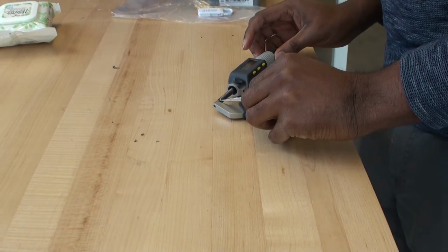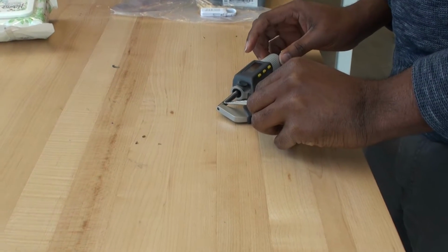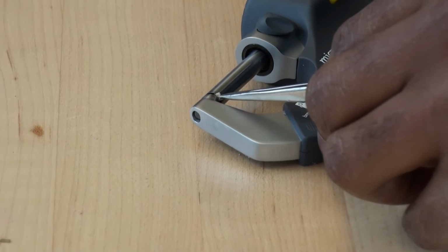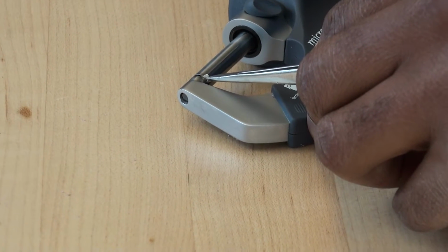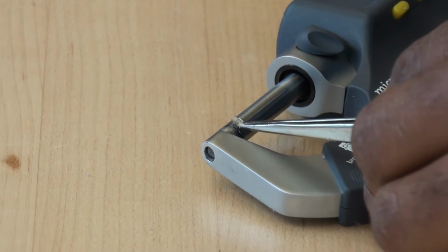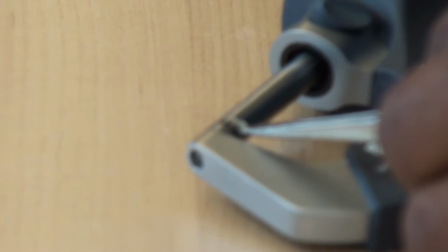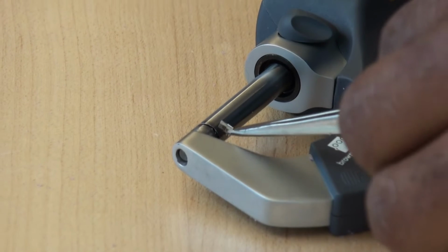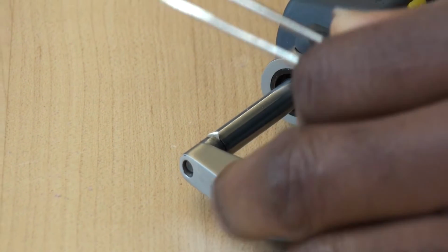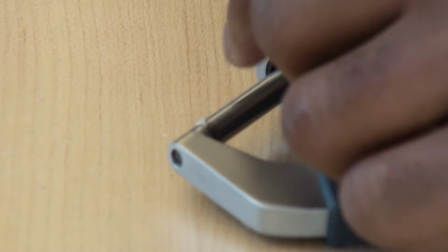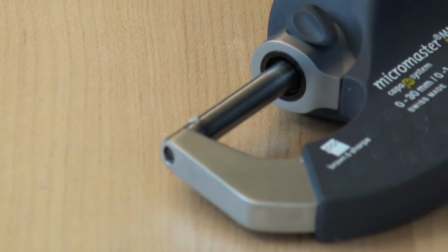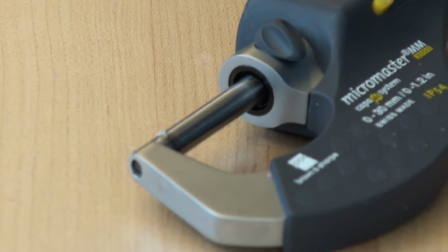So getting these chips into the micrometer is kind of a bit of a tricky business because they're so curled up. So we're using some tweezers here, and Jesse's carefully inserting it into the jaws of the micrometer and getting a reading. As you're filling this out on your data sheet, keep in mind that these are all for feed rate of 0.6. So you're filling in on the first chip we did, that was your first block off to the upper right. And now you're going down to brass for table feed of 0.6.